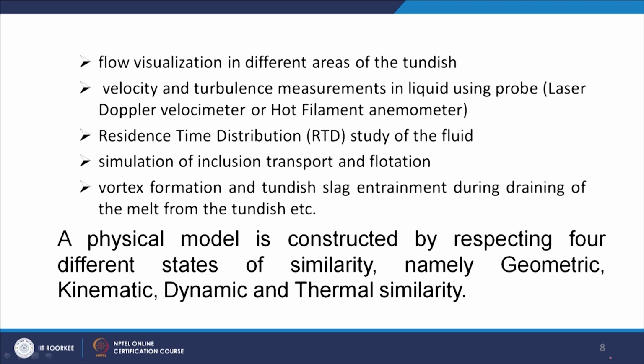Vortex formation and tundish slag entrainment during draining of the melt from the tundish. Many times when we are draining the liquid metal from the tundish to the mold, there may be vortex formation, as we discussed earlier. When the level reaches below a certain value, vortexing may occur, and in that case slag may go from the tundish towards the mold, or from any vessel into the next vessel.